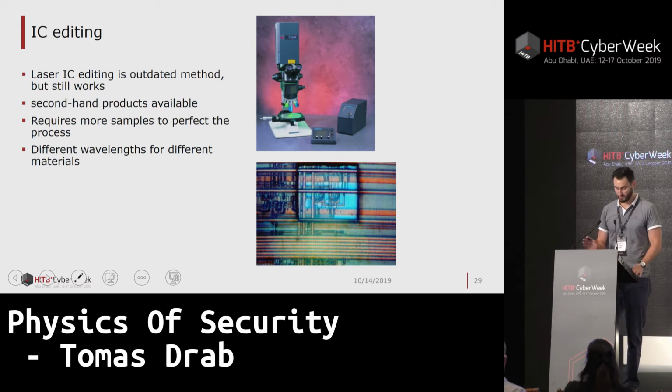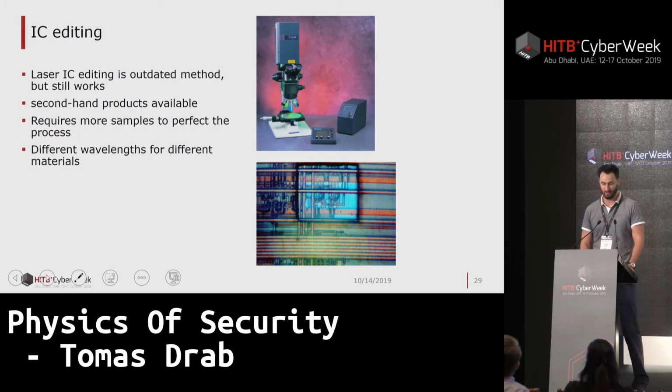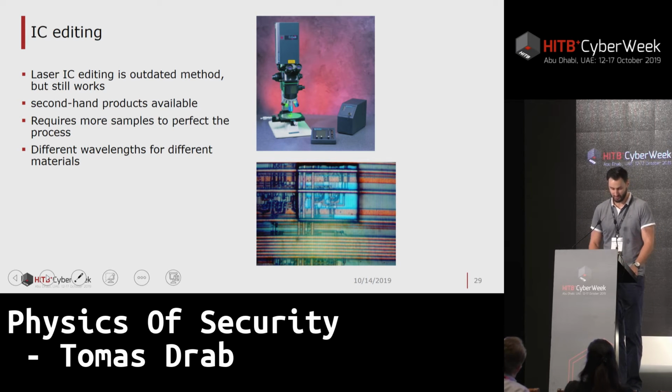Okay, lasers are outdated, at least for IC editing. That's why you can easily find them used somewhere on the second-hand market, because all these manufacturers are using FIBs now. But still, if you want to gain access just to the second layer and you just need to remove the passivation, this is a really nice tool to have.